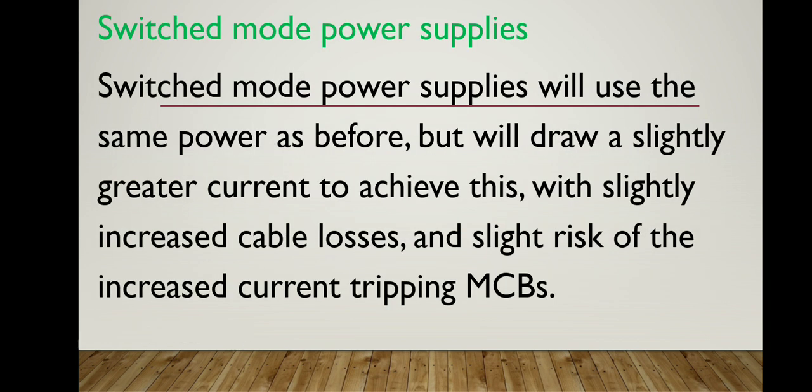Switched mode power supplies. Switched mode power supplies will use the same power as before but will draw a slightly greater current to achieve this, with slightly increased cable losses and a slight risk of the increased current tripping MCBs.